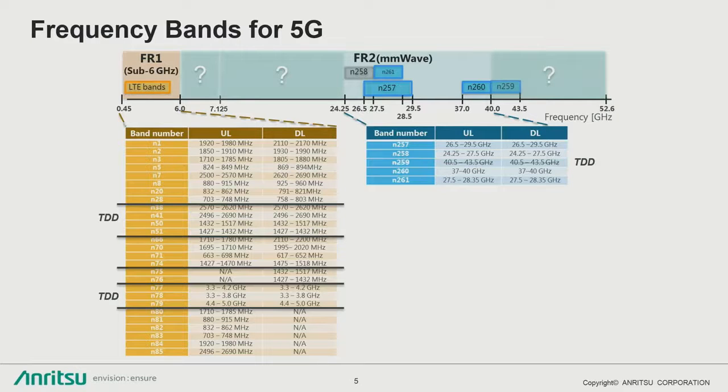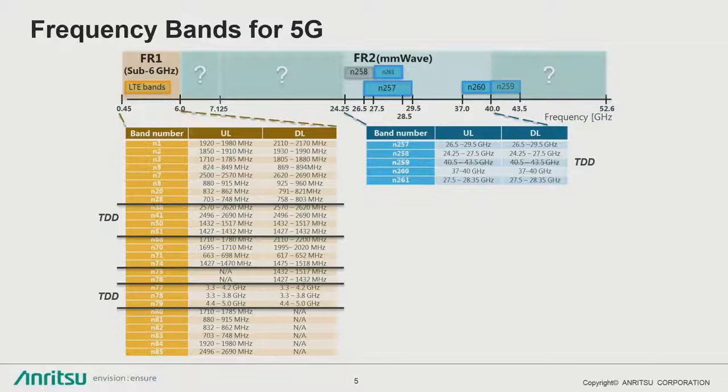This is a licensed band here between 7 and 24. There are some individuals that are talking about reusing that spectrum. If they own it, why not reuse it, right? Especially for backhaul, right? Point-to-point or point-to-multipoint backhaul. And then your millimeter wave is 24 all the way up to 52. This is all based out of the specifications. Now, everything above 40 hasn't been really defined. And 259 was on the table, and then they kind of pulled it back, and they're reconsidering some stuff.